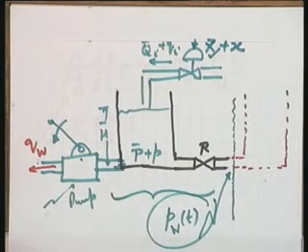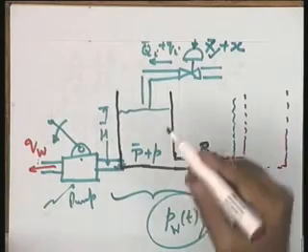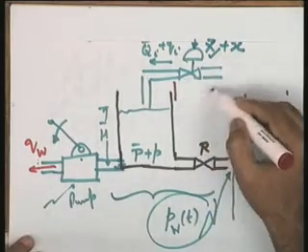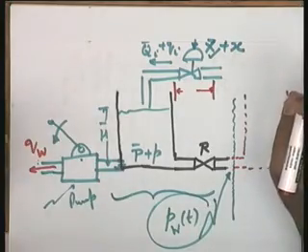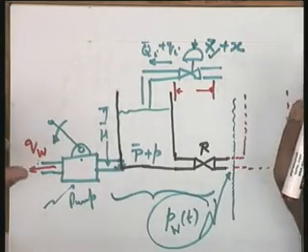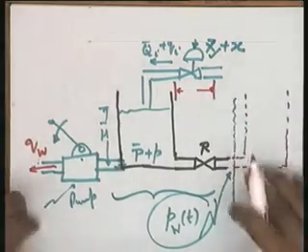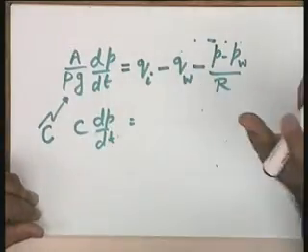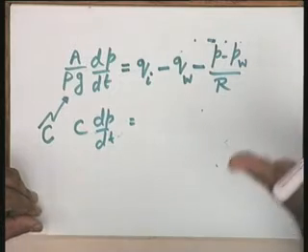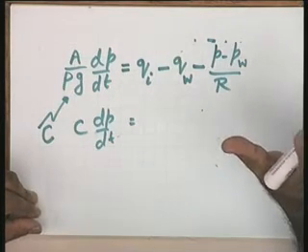In this particular case, please see the pressure differential across this particular control valve is going to be negligible. It is not going to change the pressure differential across this valve, and therefore in this situation I can write qi as a linear function of x. Again, the assumptions involved may be noted very carefully.